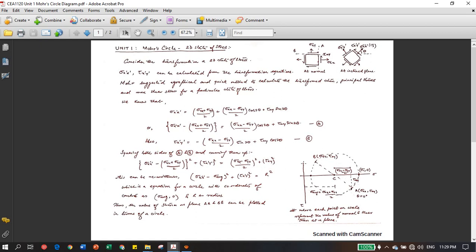So just plot a graph over here, with this axis normal stress and shear stress, and plot the points over here and join them. Then, by putting the compass over here at C and the pencil over here at A, just draw a circle, okay. And where this circle meets over here at 0, what does it mean over here, and at this point, what is this?